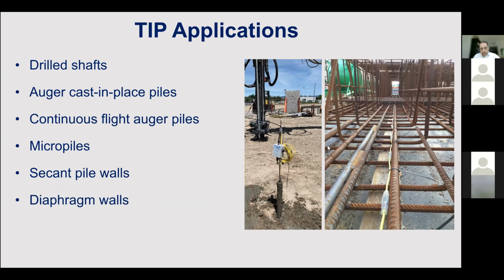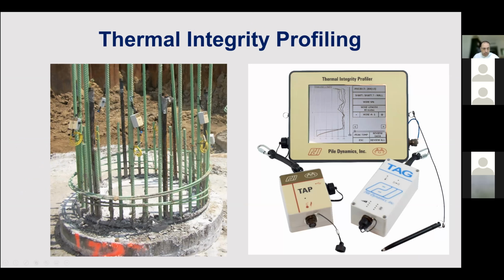This figure shows a drilled shaft installed, in which the thermal wires are connected to the data loggers. These data loggers then collect the thermal data points, automatically collected every say 10 or 15 minute intervals. It is stored within the data logger. This data logger communicates with this unit, which has cellular capabilities, with which it can transmit the data to the cloud.